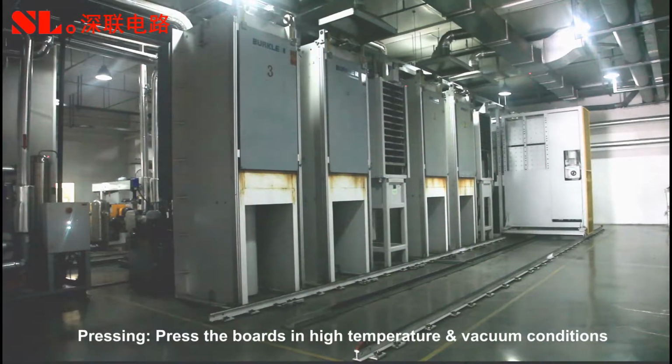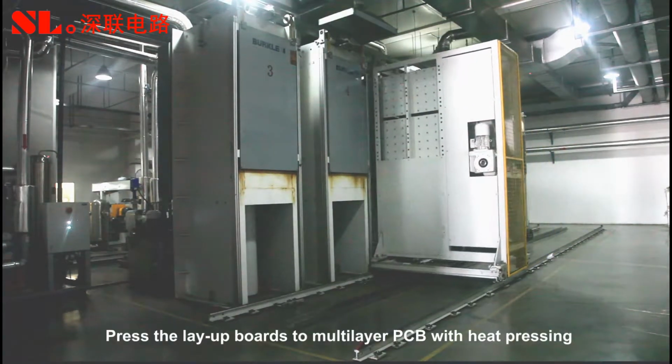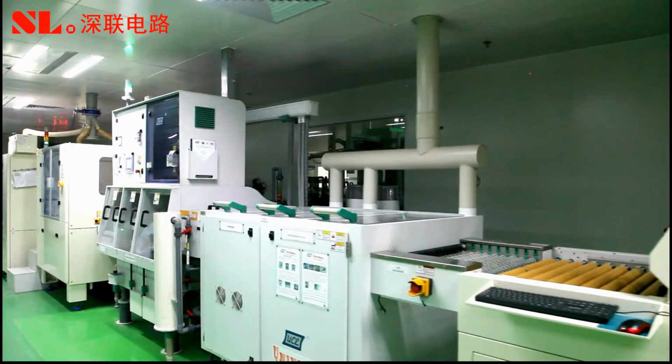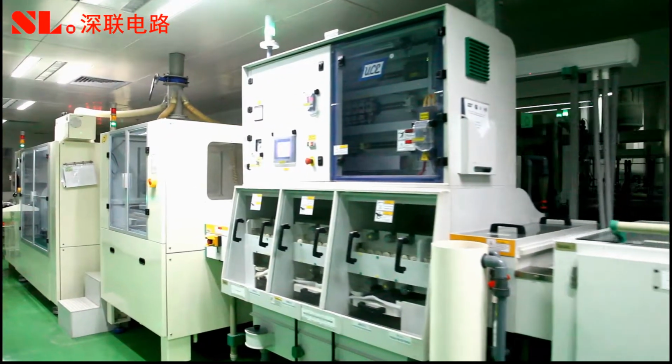Pressing. Press the boards in high temperature and vacuum conditions. Press the layup boards to multi-layer PCB with heat pressing. Cutting edge. Cut the outlines of the pressed multi-layer boards.